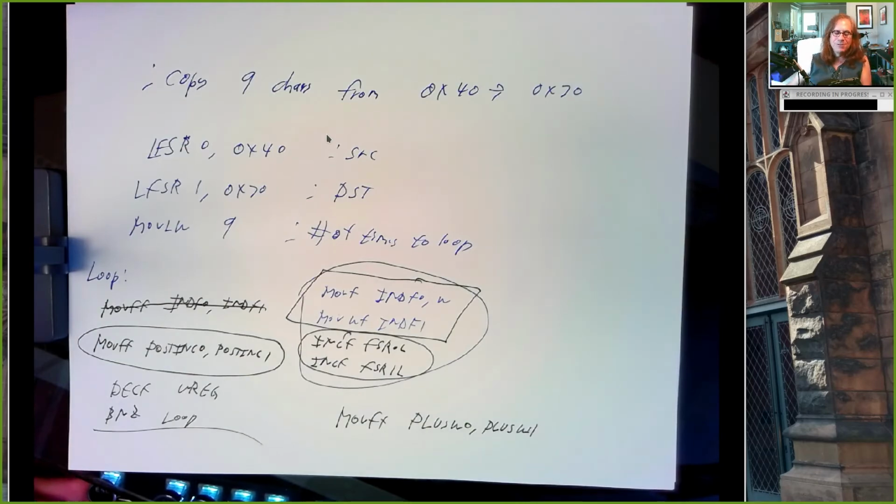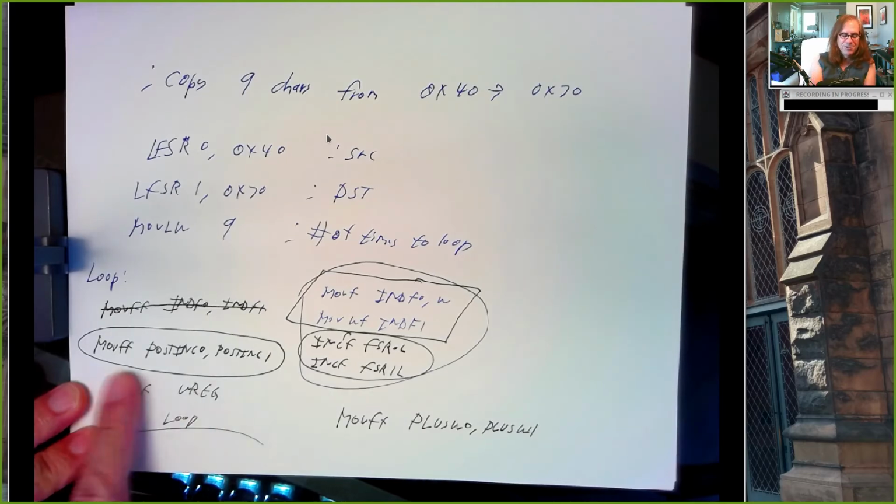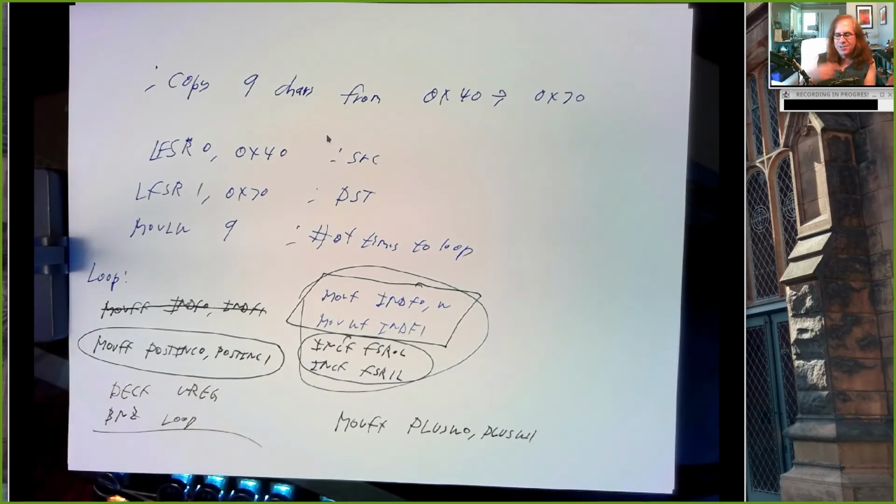So we would have to keep reusing these, just like we have to keep reusing the W register, right? W register is the only way we can load a literal, so if we want to load a literal, we've got to use the W register. If we're using W for something else, we have to save that value somewhere and then get it back later. Same thing with this. But the PIC 18F1220 gives us 3 of these, right? Which is pretty useful. Certainly you want 2 of them so you can do this kind of thing. And having the third one is kind of bonus. But on a CISC machine, typically what you find is you might be able to use any register as an indirect register.